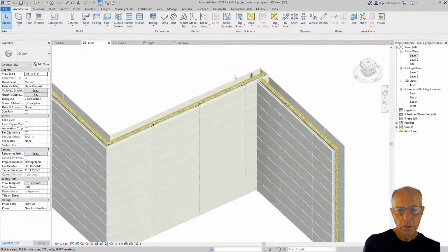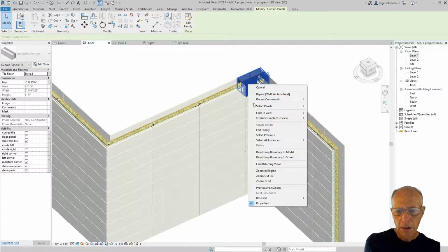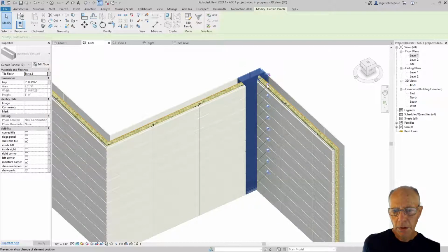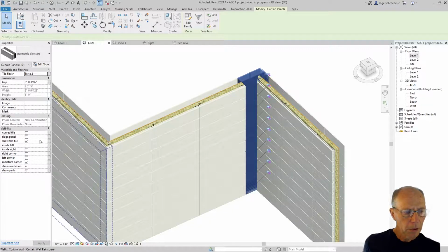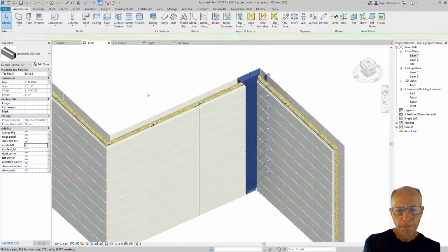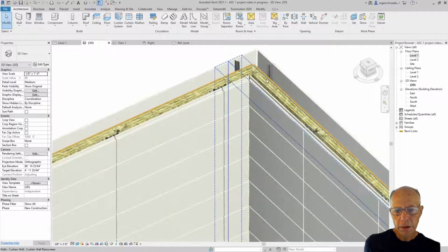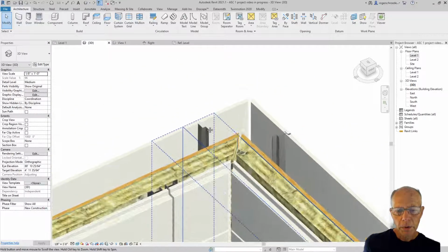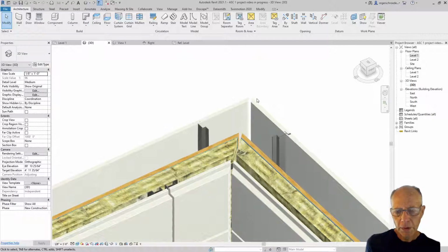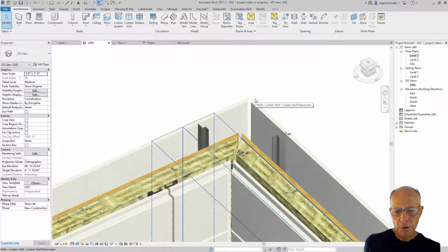Back to our 3D view. Tab. Select all vertical. Unpin them. And in the inside corner, that part is probably just going to get eliminated. So that'll be the inside left now. And there we have a nice clean internal miter all the way through, though there's kind of an issue here with the drywall. So you might want to correct that void extrusion element there.